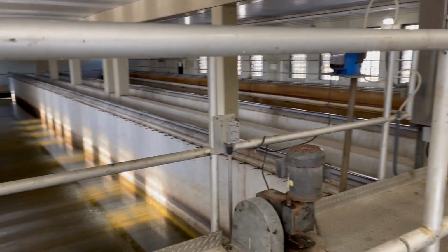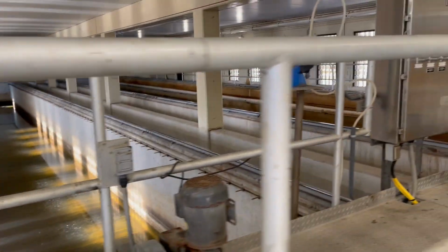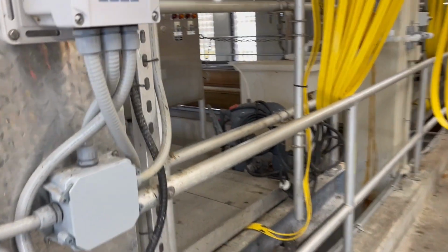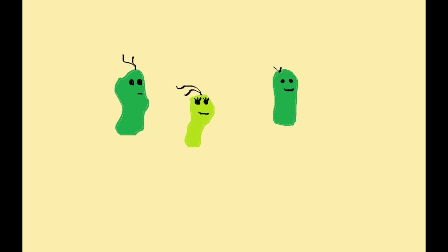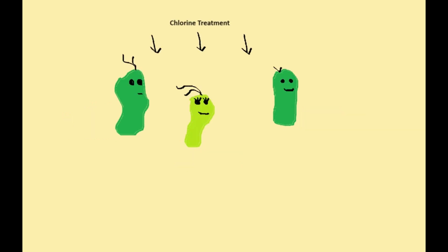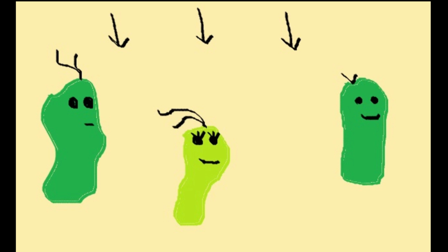In this building, the clean water is treated with sodium hypochlorite, a type of chlorine treatment for disinfection. While the microorganisms were very helpful to us in the process of water treatment, it is unfortunate that any of them that made it to this very last step will have to die to maintain adequate biological control of the treated water. The chlorine kills these microbes so that they cannot be harmful in environmental waters. Many facilities, including the one in this tour, are looking into completely relying on UV radiation as a means of disinfection, since disinfectant chemicals like chlorine can produce harmful byproducts.